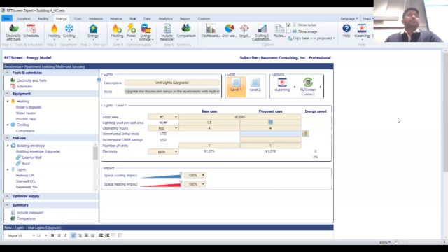As per ASHRAE 90.1, the most recent version, we know that for residential dwelling units, watts per square feet can go as low as 0.5. So we are just going to change that, and we can see lighting electricity saved almost at 66.7%, which is typical when you go from fluorescent or even incandescent lighting to LED lighting.